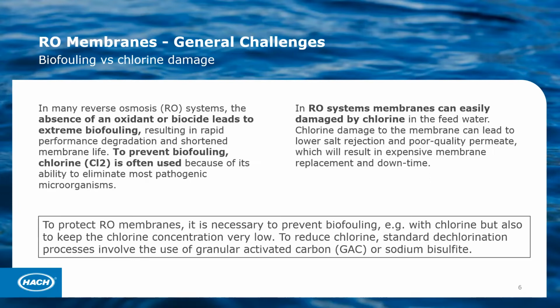But the status quo, what we see most typically, is that we are willing to deal with biofouling with the assurance that we don't completely destroy our RO membranes by allowing too much chlorine to pass through those. There's certainly nothing wrong with that. Knowing in the real world that we can only do so many things perfectly, or we can only focus on so many things at one time, that perhaps is really the lesser of two evils.